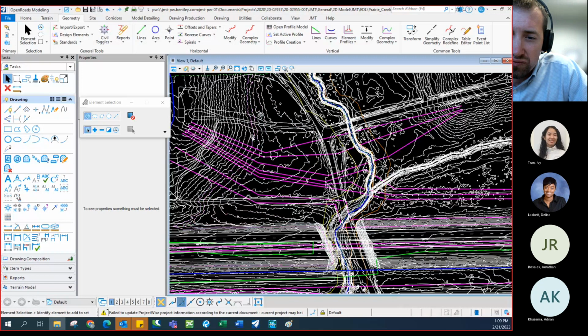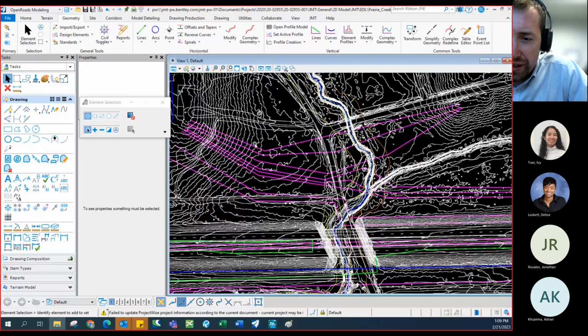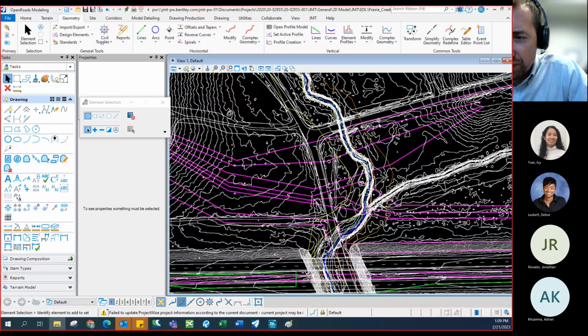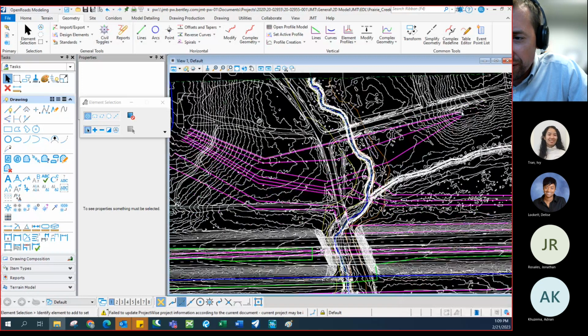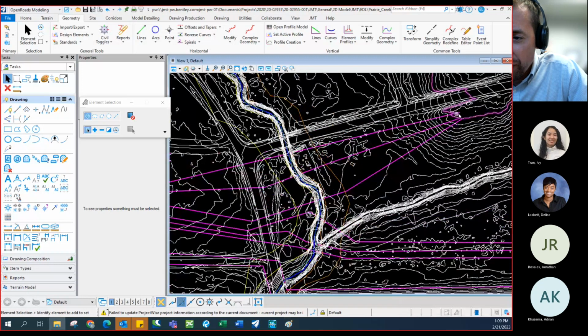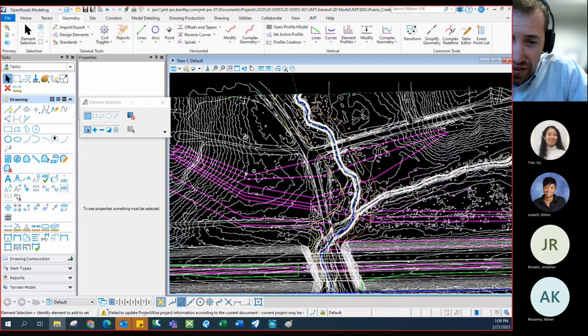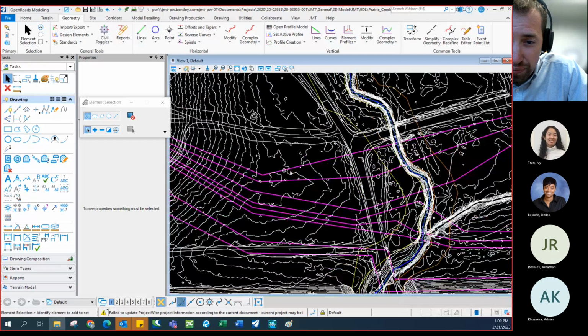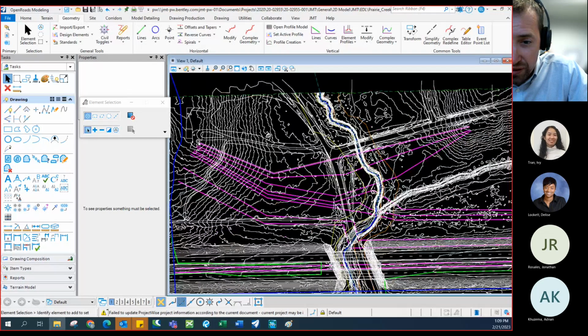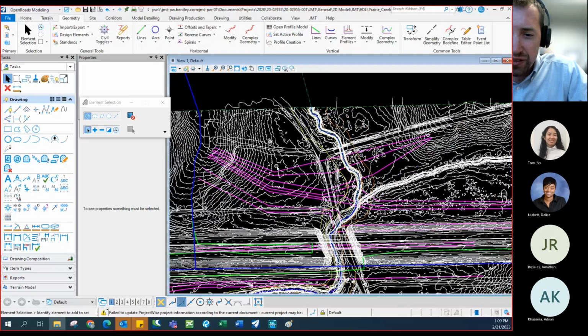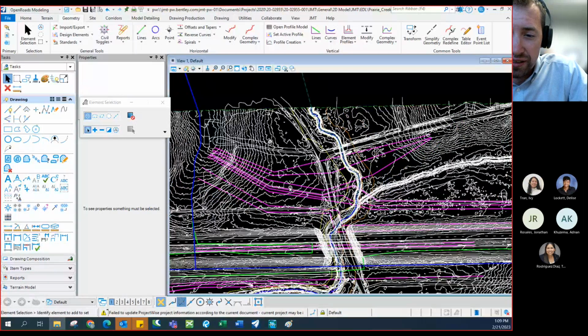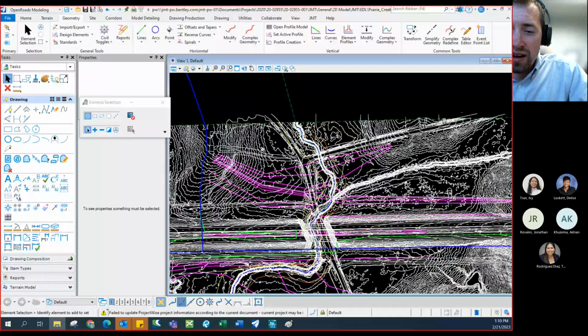So like this one, we start out on one side further than we think the floodplain is, and then we draw it pretty straight here. But when it starts having significant bends like this, we might bend the line and take it up the hill a little bit. You just have to think that way, and it becomes second nature once you've done one or two.